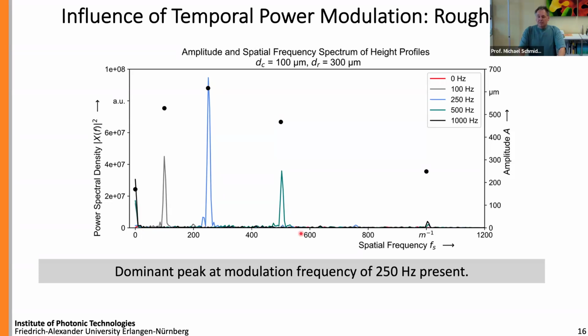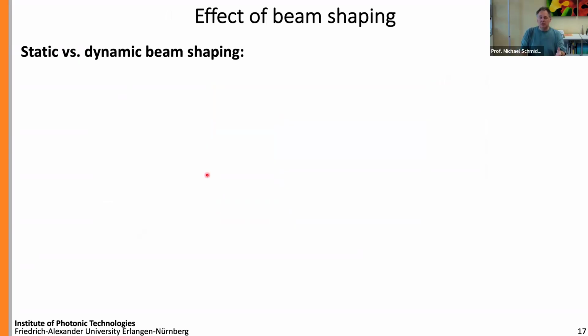It is that obviously we can influence by our spatial-temporal energy input what's happening in the process. In this case, we influence the melt. And additionally, it seems that influencing the melt works best with 250 Hertz. Maybe because this is something that is near a resonance frequency of the molten pool, which has to do, of course, with the material, viscosity, size, geometry, and so on. But this is another example that we are able to influence the process while it is running.